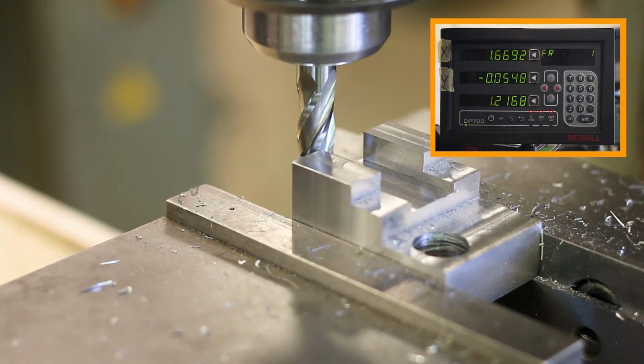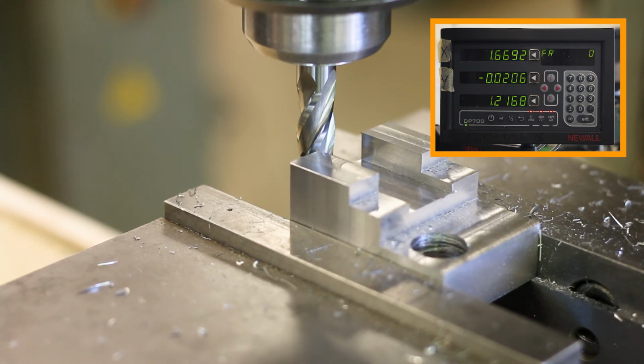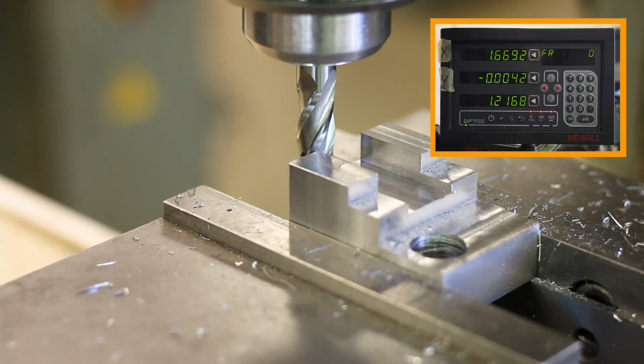So let me go ahead and bring that to 0.0005 in the minus direction. Not 0.005, 0.0005. Okay, that's 5/10 of a thousandth of an inch. And actually, it doesn't look like I get 5/10. The most that I get is 4, but that's going to be enough. And I'm going to go ahead and re-zero that.